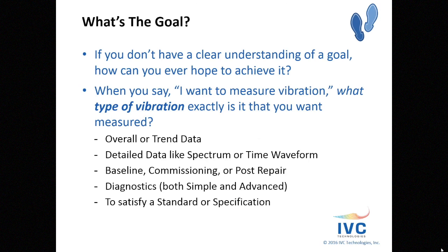So what's the goal? This is also important. You have to kind of know what my goal is so I can go about achieving it. If you don't have a clear understanding of a goal, how can you ever hope to achieve it? When you say, I want to measure vibration, what type of vibration exactly is it that you want to measure? Are you looking at measuring overall or trend data? Do you want to get detailed data like spectrum or time waveform? Those may require additional types of instruments or specific types of instruments.